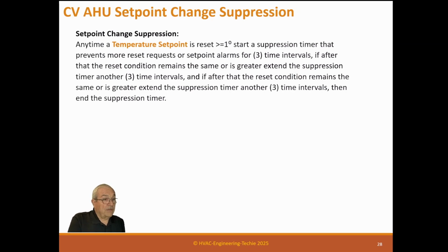Now, you can suppress other things like duct static pressure, but I don't normally do that because it's really tightly contained and it can be affected very, very quickly. So it won't have a large mass like a room does. It will happen very, very quickly, so I don't see any need to put a suppression on that. You could do room humidity, but my sequences in this video don't actually reset humidity like this temperature reset. It's a different kind of reset altogether. It doesn't need to have this suppression.